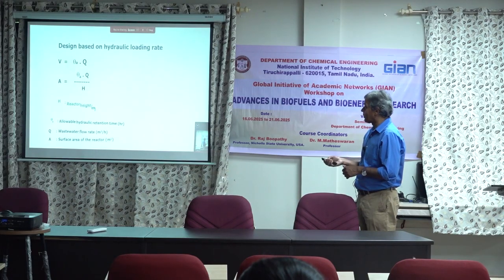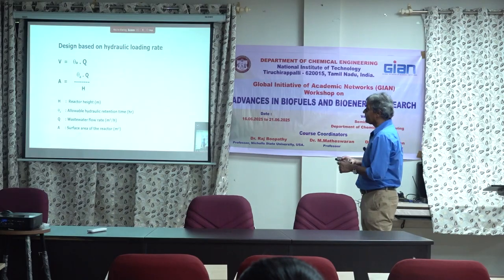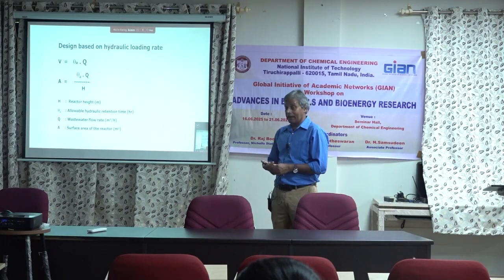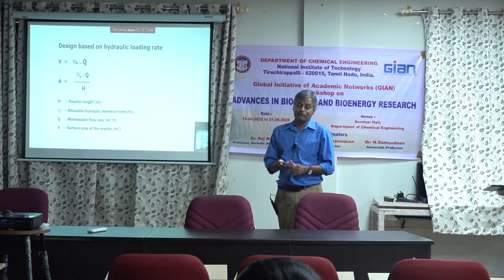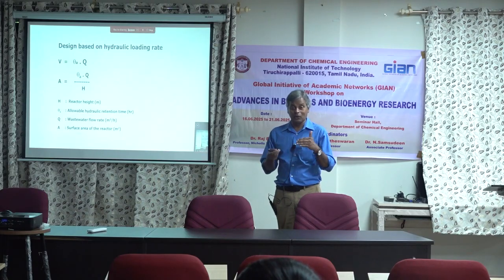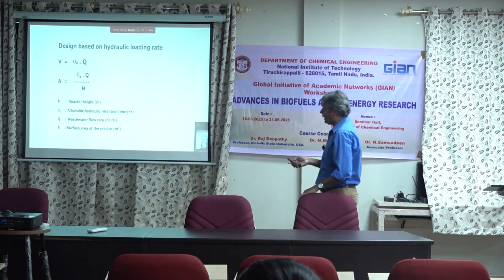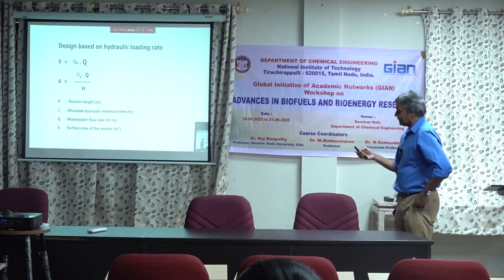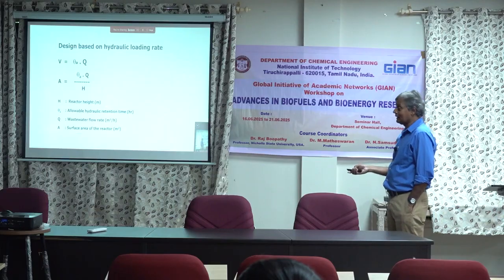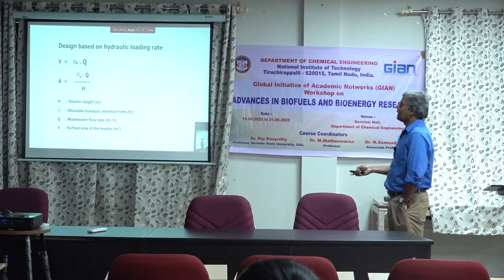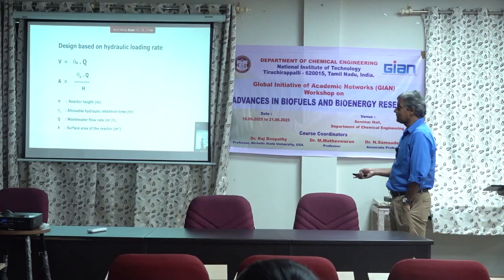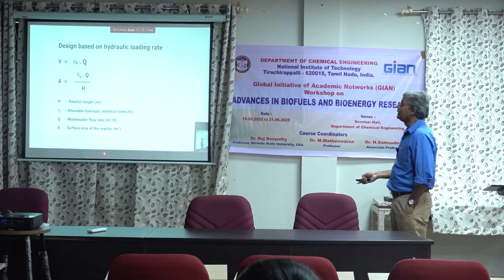I will ask you to solve the problem. The second one is designing based on hydraulic loading rate. How long is the water going to spend inside the reactor? For that, you need to know these parameters: reactor height in meters, allowable hydraulic retention time in hours, wastewater flow rate, and surface area of the reactor in square meters.